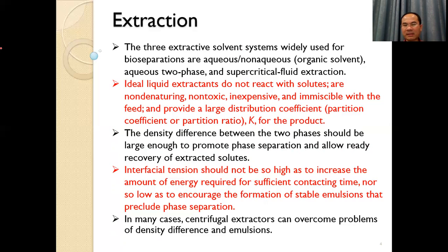And also the density difference between the two phases should be large enough to promote phase separation. After we mix this system together, we finally have to separate by phase separation. The heavy phase should be at the bottom and the light phase at the top, so it's easy to separate for the next step. And also the interfacial tension should not be so high. If the interfacial tension is so high, that means we need energy for surface and contact time, which is high energy in that case.